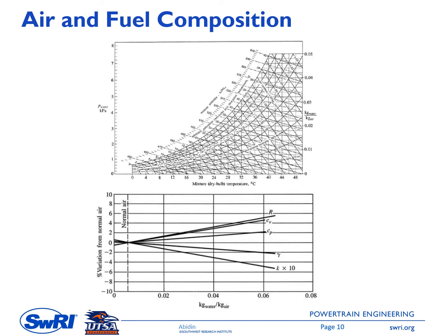And then what if we have wet air? Then we use a psychrometric chart to get the properties of this wet air for given two properties. This is an example of the psychrometric chart. I think you know this chart in Thermo 2. On the vertical axis here we have a kilogram water per kilogram air ratio, which is called humidity ratio.